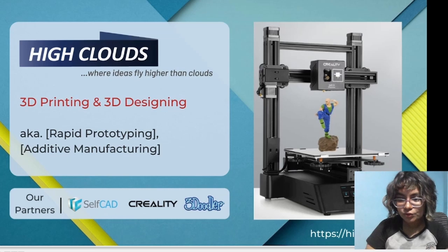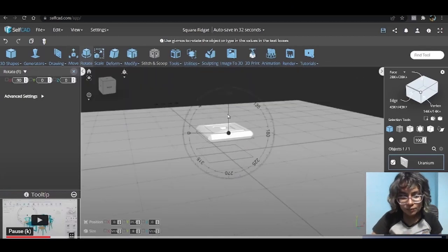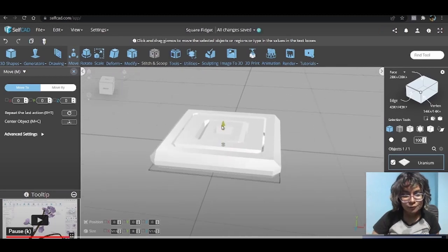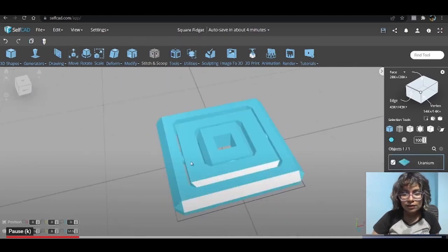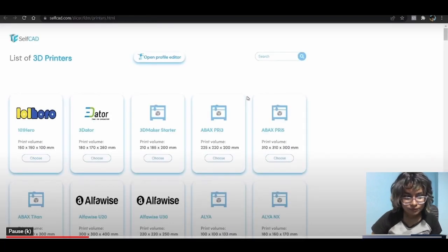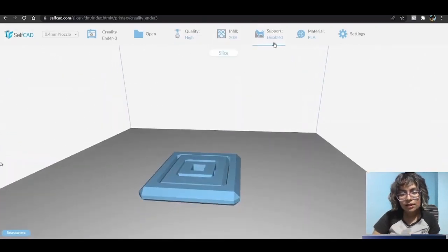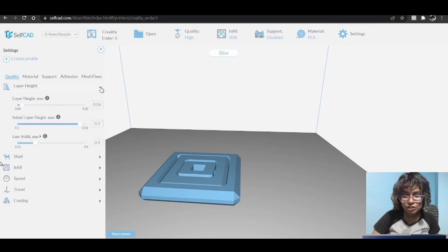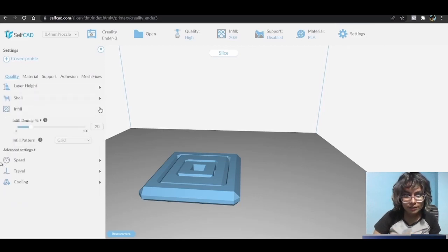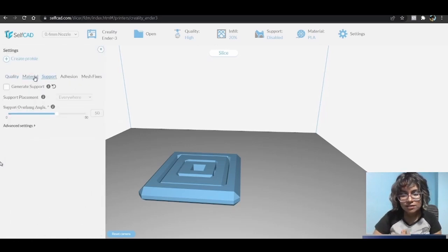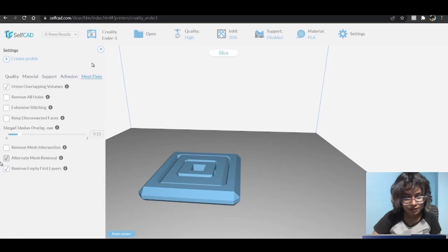Today we are going to talk about 3D printing, rapid prototyping, additive manufacturing, etc. So 3D printing simply means that a 3D printer can automatically make an object out of a CAD model that can be designed in your laptop, computer or desktop. The CAD model is basically sliced in a slicing software. Slicing means the 3D CAD object can be virtually sliced into multiple horizontal layers, and this is exported as a G-code file. G-code file basically acts like an instruction for the 3D printer to automatically print that object.